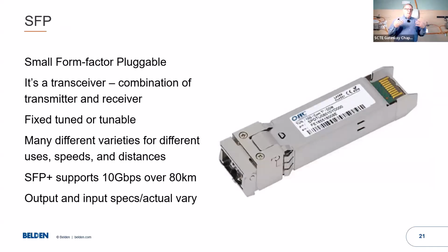Fiber optics plug into SFPs, nodes, head ends, and now sometimes in people's houses. An SFP is a small form factor pluggable, a transmitter and a receiver built into one. We're talking about SFPs because if you don't deal with them and you get an outage one day and you don't have the spare, some places there's not a lot of spares, so they're actually being stored at the office or something.